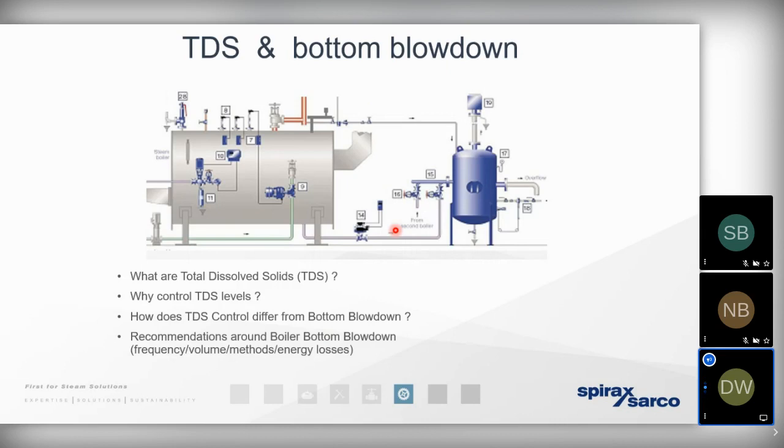So we can keep that bottom blowdown to an absolute minimum by upgrading the controls, by moving away from a manual valve to a valve with a timer on an actuator, so we can ensure that the blowdown is kept to the prescribed minimum. Now, we also know we blow down from the side of the boiler, and that's to address the total dissolved solids. And that's because some of the chemicals and minerals will be held in suspension.